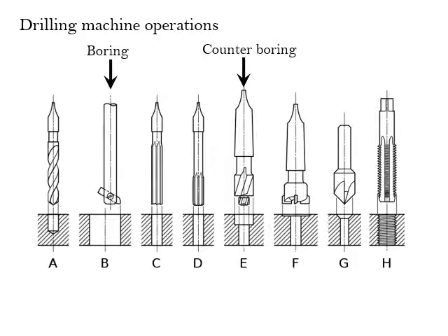Second one, counter boring. Counter boring, you can see this figure and understand clearly. It is not a straight line. Some of the area, some of the portion is an enlarged hole and the remaining is a different diameter. Suppose this is 10 mm, and some area will be 20 mm. That process is called the counter boring operation.